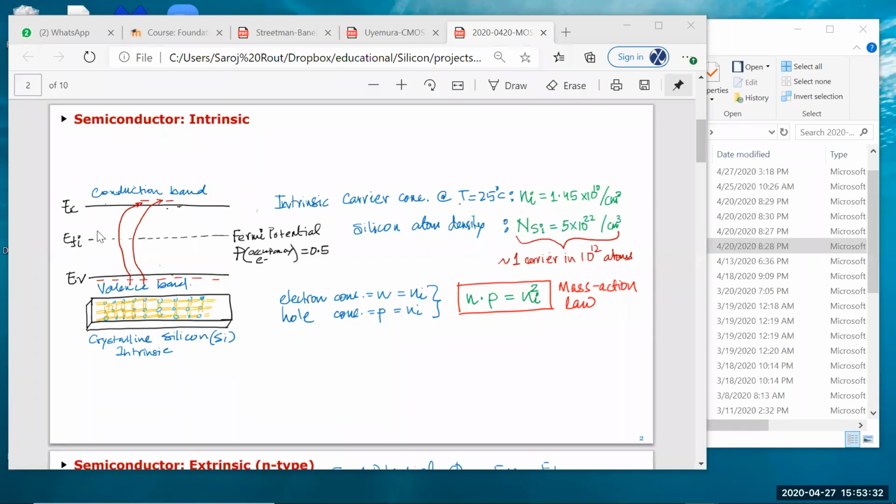So in a band diagram, what you see is a band of a particular material, for example silicon. You see this band gap is 1.1 electron volt, which means that in this particular band, there can be no electrons at all. That's just not possible from the physics of the atoms and their interactions with the lattice. These are the possible energy states: anything below the valence band, anything above the conduction band.